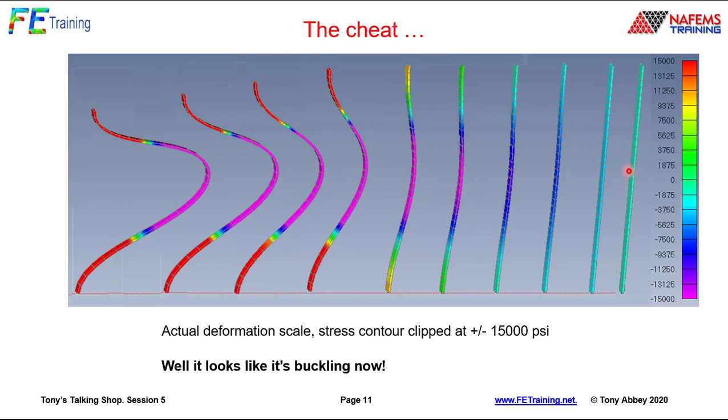buckling actually looks pretty good. This is over on the right hand side here, the initial condition, and then this is the buckling that's carrying on. You can see it gets to a pretty wild shape over here. Now I can actually chase that buckled shape through, and it's developing a particular, and now it is a true shape. These are actual deformations. It's not an eigen mode or an eigenvector, which we have from the linear buckling analysis.